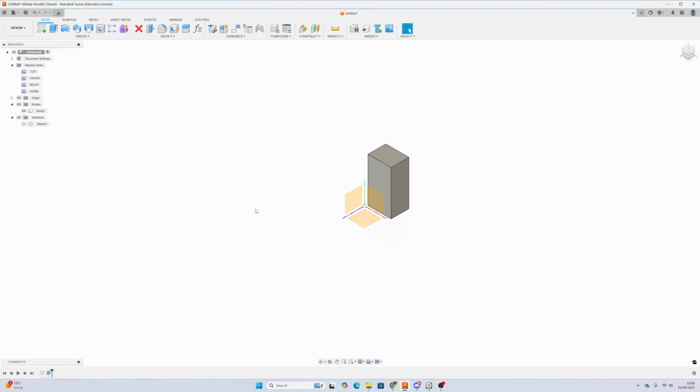Next up after that is the canvas and marking menu. So if you right click on your mouse button, you will get pretty much a summarized version of all of the different processes and tools that Fusion has to offer, including some of your movement tools like pan, zoom, constrained orbit. You can also change your workspace and have easy access to some of your process and some of your modeling tools. So let's start modeling this tutorial block.